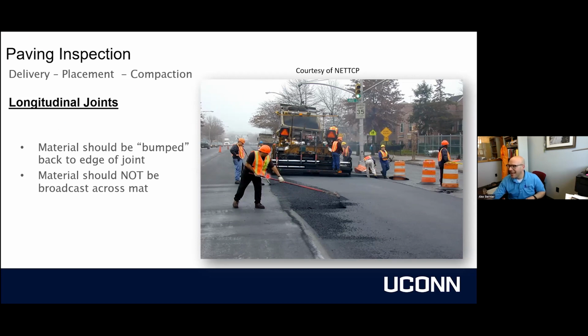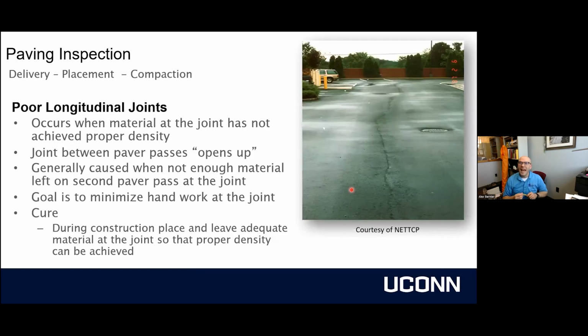You can also see, besides the fact that all that material is being pushed away, he's creating segregation, right? There's large stones being cast out onto the mat. And you will actually see shadowing on roads as well when this has been done. Broadcasting material, bad times.